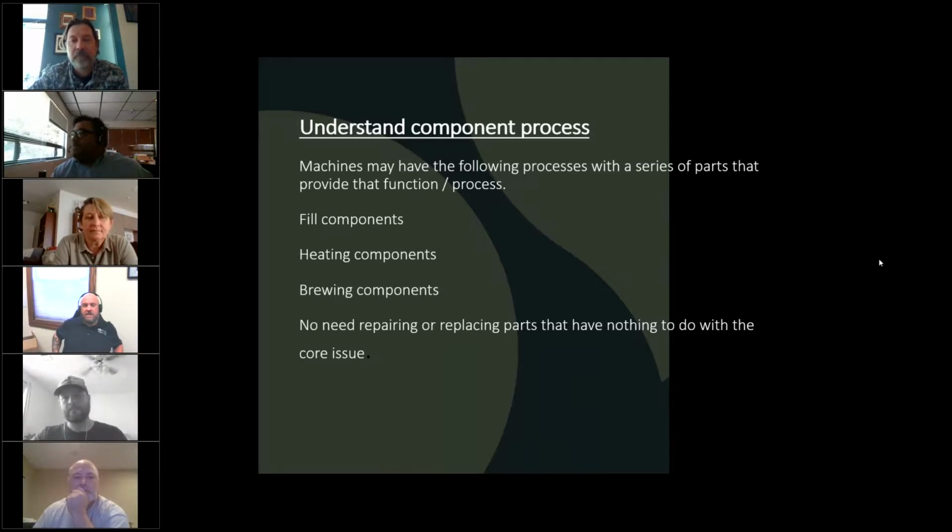I don't go, oh, that error code tells me to replace this part. No, it just tells me what circuit I'm probably looking at, is all I think of it for. Gives you some direction. I would say it depends on how complex the error code is too. Some units will have more definition attached to each error code, and if that helps you find a little bit more, it gives you more context clues. Use it to your best, like Bert was saying, as a hint as to where you're going. It may help ease your process.